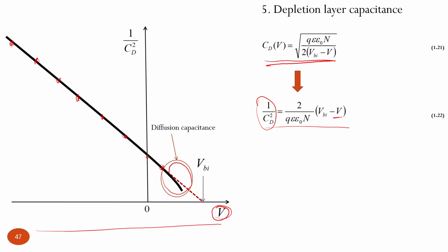That is because of the so-called diffusion capacitance associated with injected charge carriers at forward bias. So we inject charge carriers and then extract them. That is associated with some change of electric charge, because we add and then take it away. If we have processes that change electric charge because of changing voltage, it automatically behaves as a capacitor.